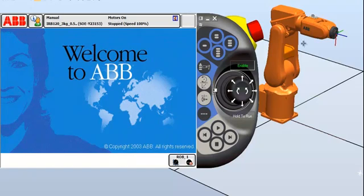In this simple program, we're going to move the robot down to the pickup location. Let's say it's over here somewhere. We're going to do a joint interpolated move, then a linear move down to the pickup location. We're going to move back up with a linear move over to the place location and do the same over there. Obviously we don't have any tooling on here. If we had tooling, we'd want to activate the tooling at the pickup location and at the place location.